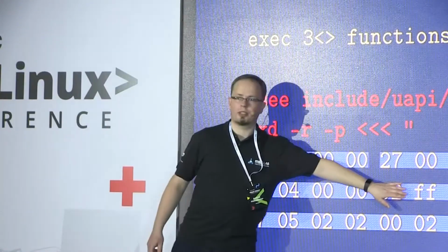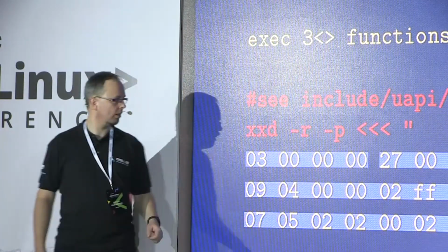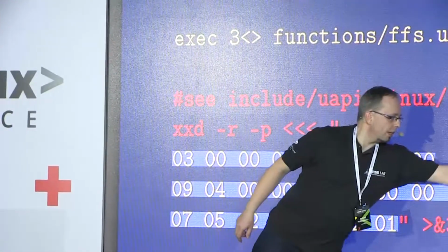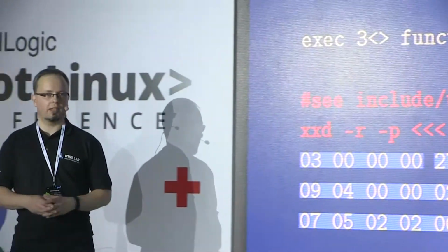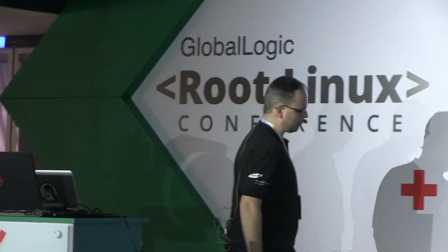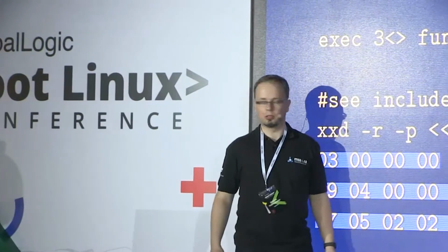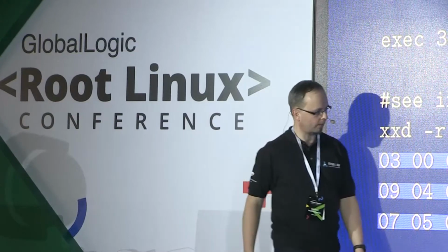Number FF here says it will be vendor specific class. Our function is very specific. And number 81 and number 02 here specify the descriptor address and direction. In a very similar way, we specify strings. So number 2 for strings, 20 is 32 decimal. There are 32 bytes in this block.